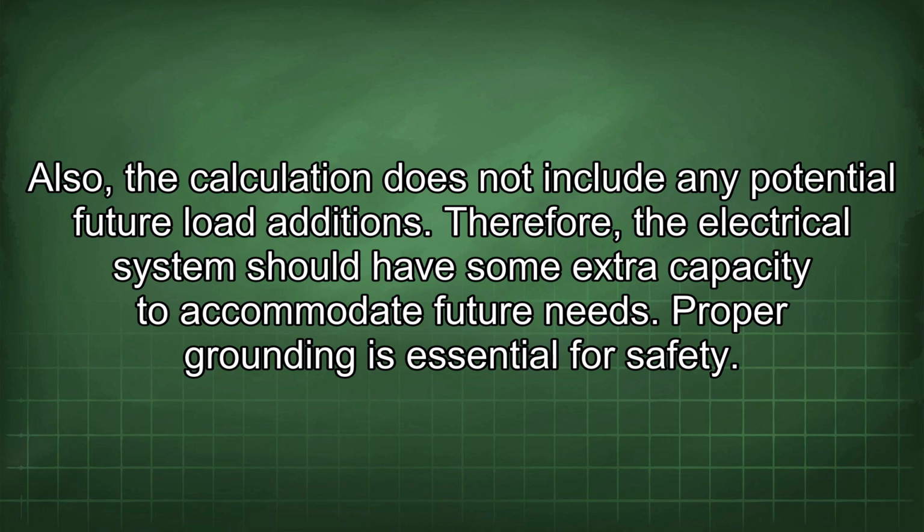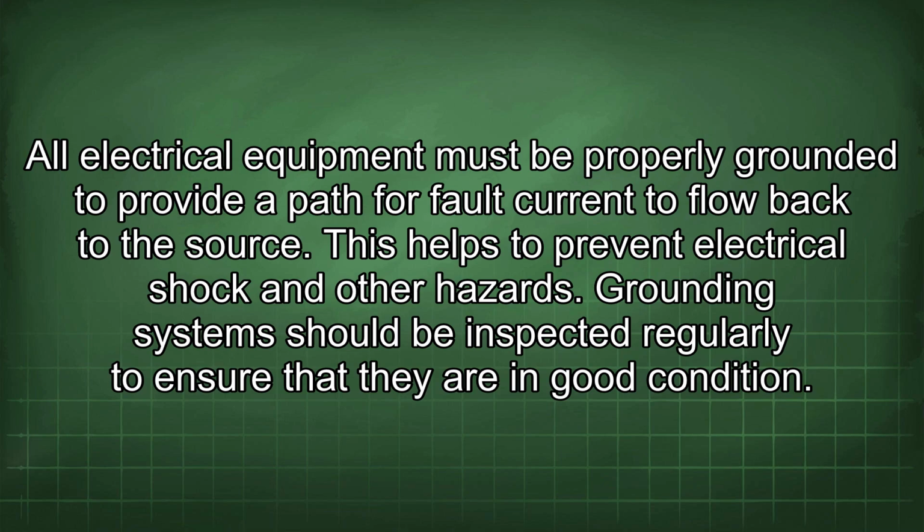Therefore, the electrical system should have some extra capacity to accommodate future needs. Proper grounding is essential for safety. All electrical equipment must be properly grounded to provide a path for fault current to flow back to the source. This helps to prevent electrical shock and other hazards. Grounding systems should be inspected regularly to ensure that they are in good condition.